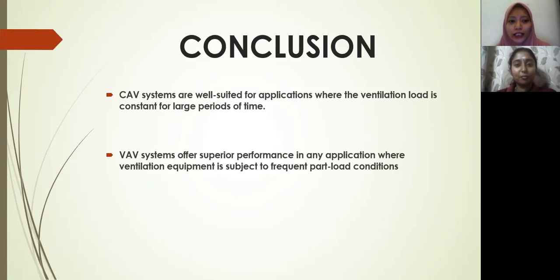For conclusion, the CAV systems are well suited for applications where the ventilation load is constant for large periods of time. VAV systems offer superior performance in any application where ventilation equipment is subject to frequent part load conditions.